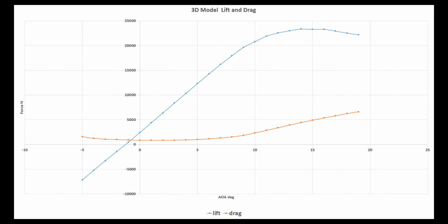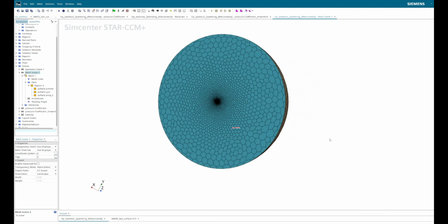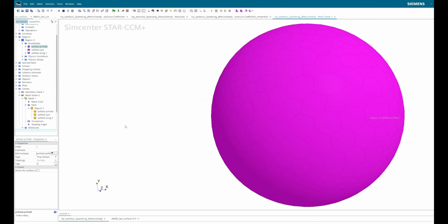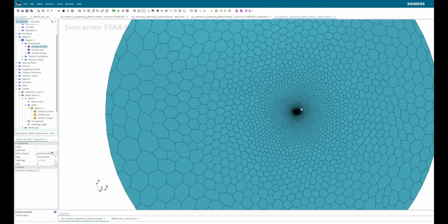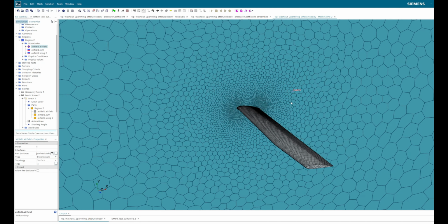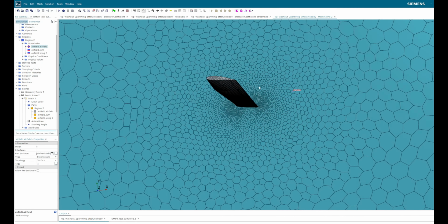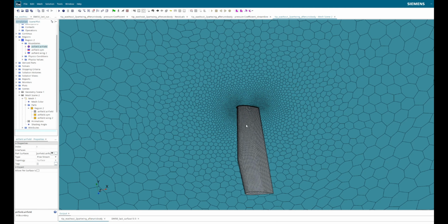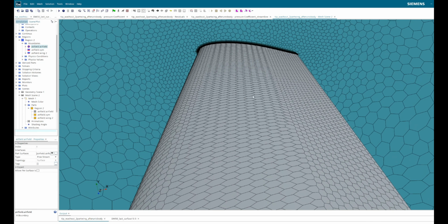Finally, the computation also provided the total vertical and horizontal forces on the wing, namely the overall lift and drag, as well as the pitching moment at the wing root. These more accurate values can be used for basic flight performance validation. To prepare for the semi-fluid structure interaction, these overall forces need to be broken down through finite element methods into point-based loads, so they can be imported into the structural model with higher precision.